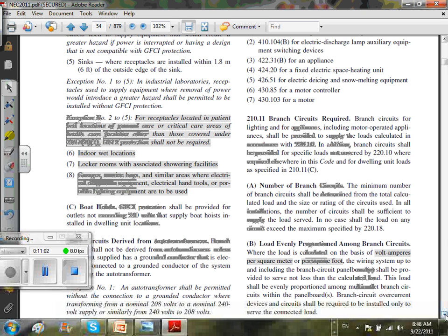Which tripped, the circuit breaker or the GFCI? The circuit breaker. So you overloaded the circuit. It's just too much stuff on it. It would be a good idea to put it on a dedicated circuit. Right, because if you've got a guy tooling around in his garage with a bunch of tools, motors and everything, you can easily exceed that.